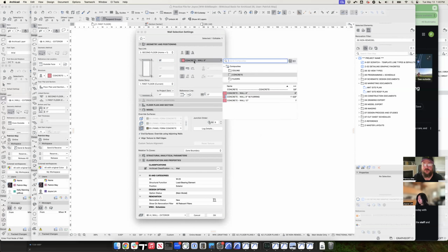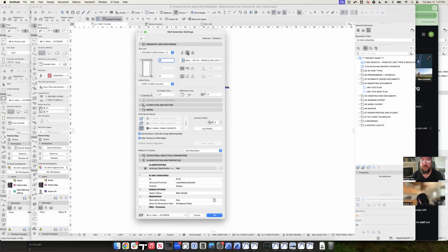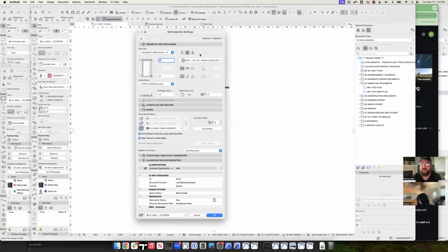Most of the composites are going to be things like our exterior 2x6 wall. These can have all of the various layers over the top of them, right? So it can have the siding over the sheathing over the studs, chipboard, tile, whatever we need. These can be built up out of complex extrusions, but they're all parallel extrusions. There's no complex shape. And the third option is actually a complex profile, and that can be any shape that you draft.